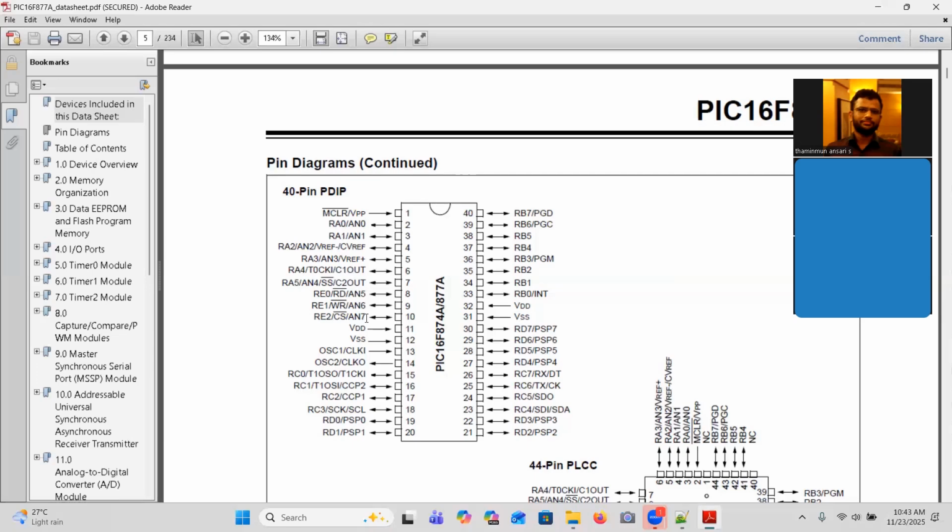So these pins are used for analog to digital converter interfacing. That means the sensor input. You can receive input from 8 different sensors in this microcontroller. That is more than sufficient for a small implementation right now. But you cannot digitize all of them at the same time. You have to do it at different times. So you have to do time division multiplexing, right?